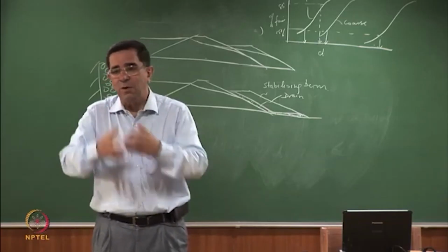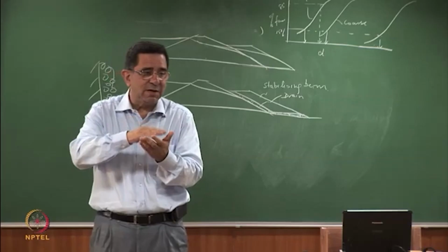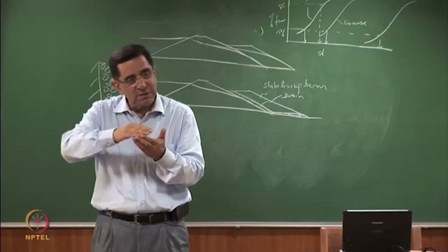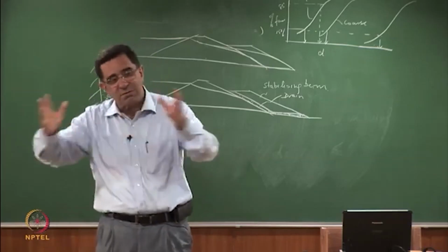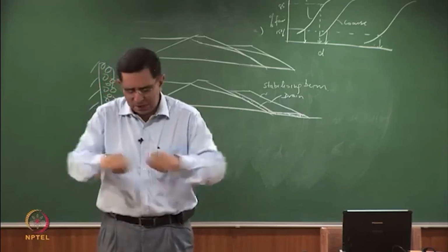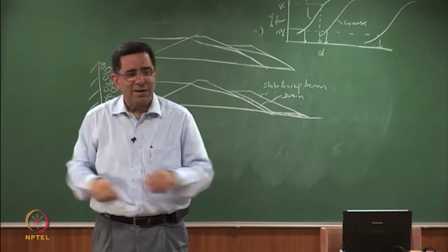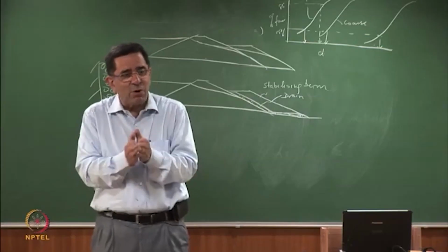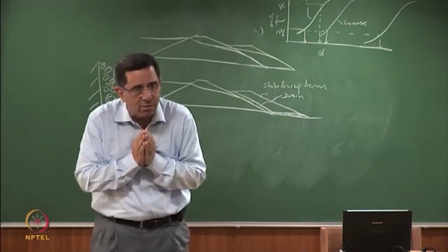2 mm or 4.75 mm. That's the difference between gravel and sand. So from 4.75 mm to 300 mm, you can get sieves of any size. If you don't get them, please manufacture them. Take strips of steel and make, suppose you want to make a sieve of 100 mm, how will you make it?